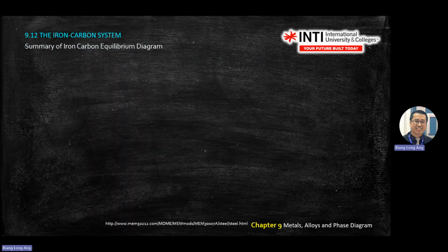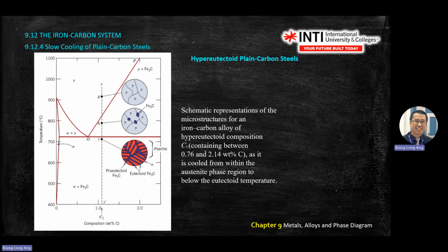Okay. Again, it still forms pearlite, but different things. For example, here you don't see alpha. Hyper, you don't see alpha, but hypo you will see alpha. You'll go through alpha. Hyper, at least, you don't see any alpha here unless you reach this, after this 727 degrees C, then only you see alpha. So don't confuse between hyper and hypo.